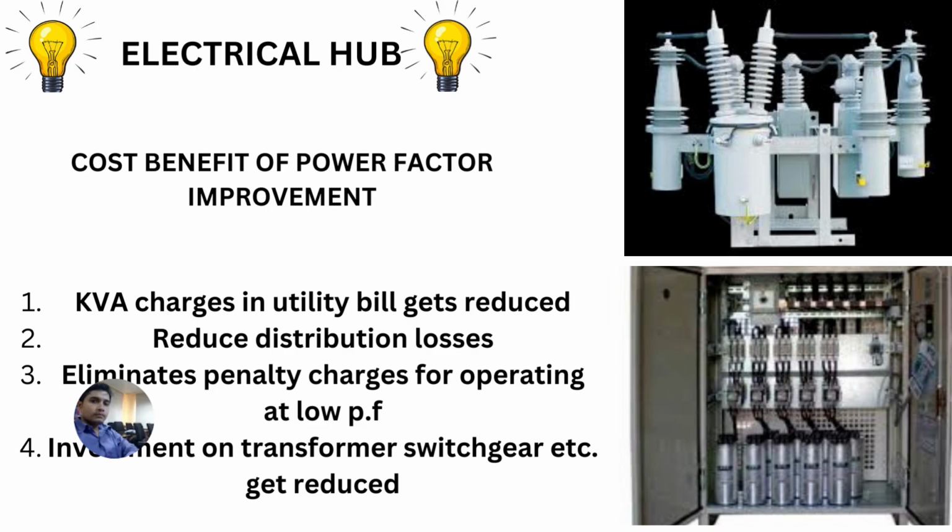Thirdly, it eliminates the penalty charges for operating at low power factor. It also reduces the direct investment on transformer or switchgear because due to the improved power factor we can use it at its optimum capacity.